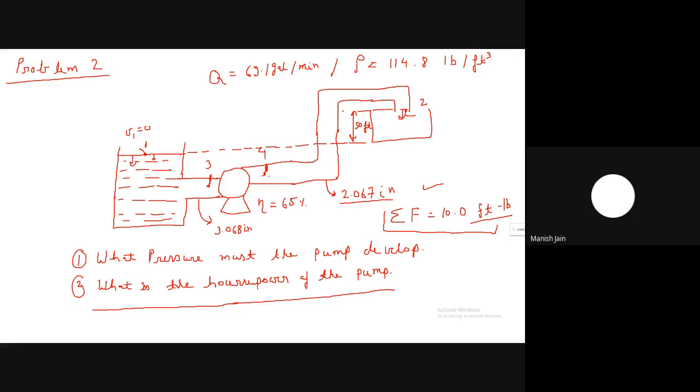The second thing is velocity, the kinetic energy, that will be different. And the loss due to the friction force is 0, because only the pump is present between the flow. There is no joint, no pipeline present between these 2 points, so we can assume there is no friction loss. So the only difference is the velocity, the kinetic energy between these 2 points.